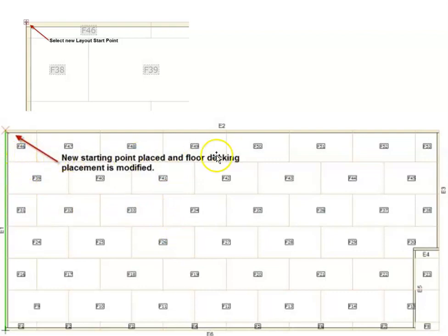This is a 4x8 sheet of plywood right there. When this is getting laid down, this seam can't be in line with that seam. The seams have to be staggered over to here, so that is staggering the seams. That is why the carpenters decided to start here with a 4-foot piece.